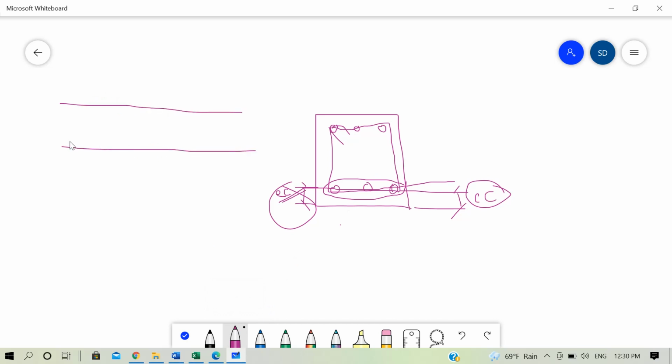If we go again here, this is our slab. Here we have bars in the shorter direction. We saw in our previous lecture of this series that the shorter bars are always kept at the bottom, followed by the longer side bars at the top, and those two bars are tied properly. So this bar at the bottom is the shorter bar, and then we have the longer direction bar at the top. Let us suppose that both these bars in the shorter and longer direction are 8 mm. So what will be our effective depth then?